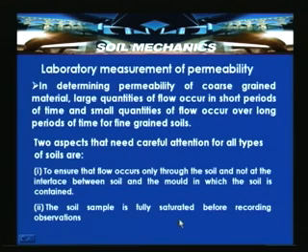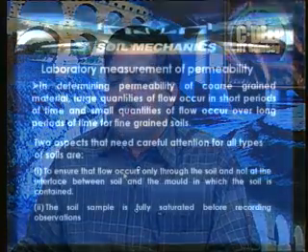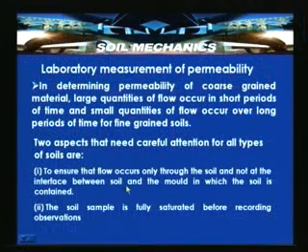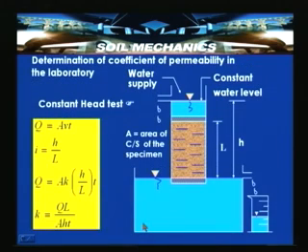The importance of saturation of the sample is very much required. Otherwise, the air in the soil voids can influence the permeability value, and can hinder or influence the flow channels which are developing through the soil mass. So, the two aspects are: ensure that the flow occurs only through the soil, not at the interface between the soil and the mould in which the soil is contained, and that the soil sample is fully saturated before recording observations.